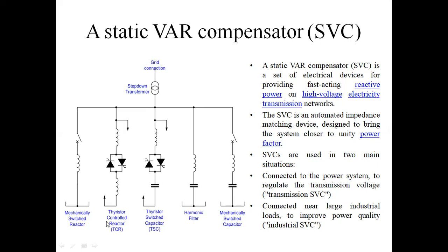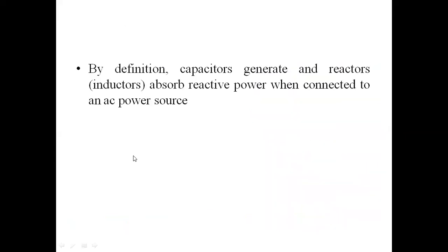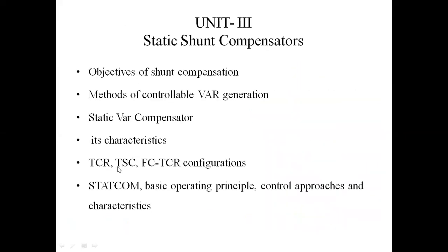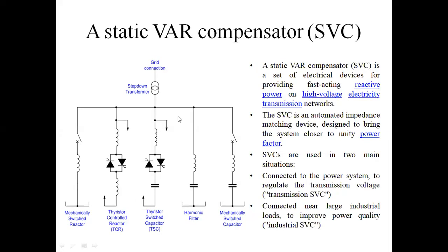In this SVC, the subtopics are thyristor-controlled reactor, thyristor switched reactors, harmonic filters, and mechanically switched capacitors and mechanically switched reactors. Subtopics here are TCR, TSC, FC-TCR.